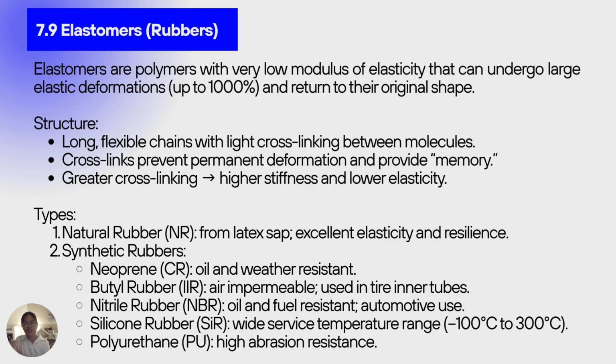Elastomers have several distinct properties that make them irreplaceable in engineering applications. First, they have extremely high elasticity. They can stretch up to 1,000% strain and recover completely. They deform easily under small loads, making them ideal for absorbing shock and vibration.